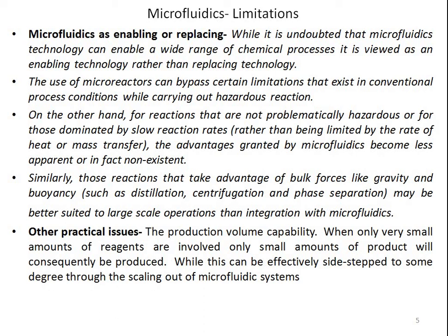Of course, these are true process conditions while carrying out hazardous reactions. On the other hand, for reactions that are not problematic or hazardous, such as those not highly exothermic, or those dominated by slow reaction rates rather than being limited by the rate of heat or mass transfer, the advantages granted by microfluidics become less apparent, or in fact non-existent. Similarly, those reactions that take advantage of bulk forces like gravity and buoyancy, such as distillation, centrifugation, and phase separation, may be better suited to large-scale operations than integration with microfluidics.